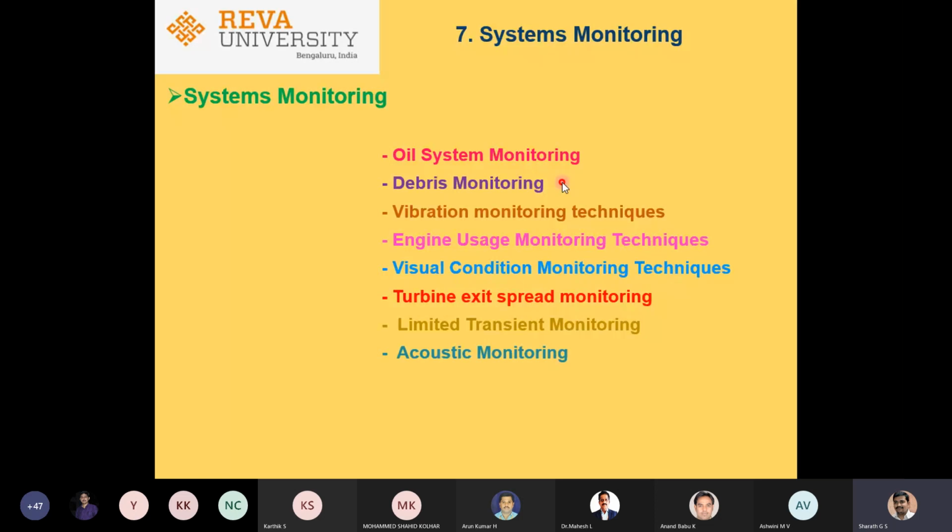This can be identified from components like the centrifugal breather, wherein you will have more air because the air is trying to stop the leakage of the oil, and so it has to separate the air and oil over there. There we can identify if there is any damage to the oil system.